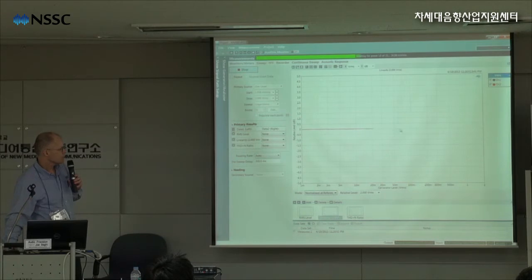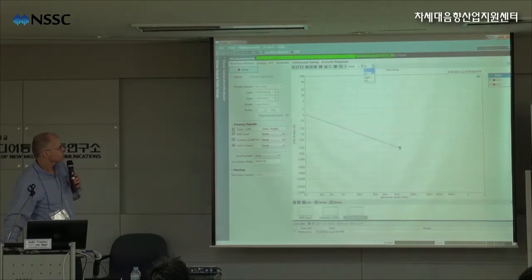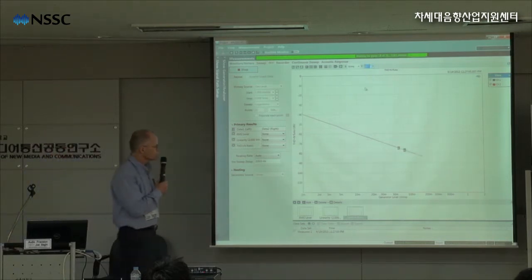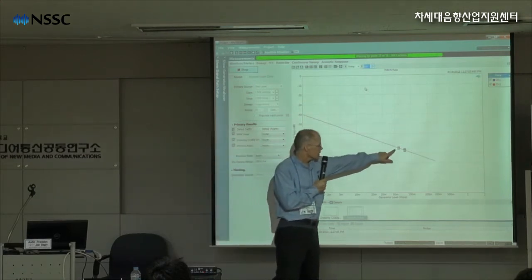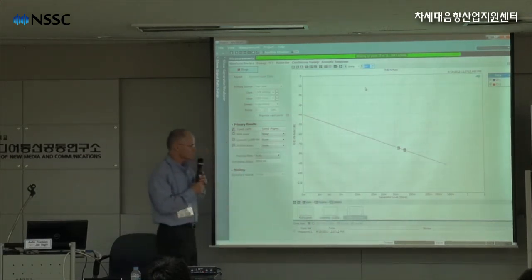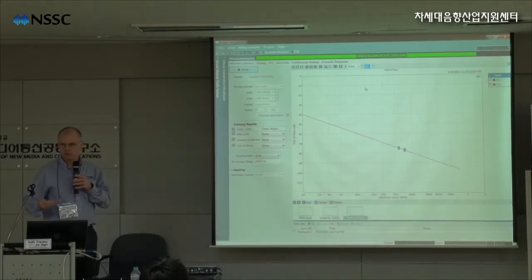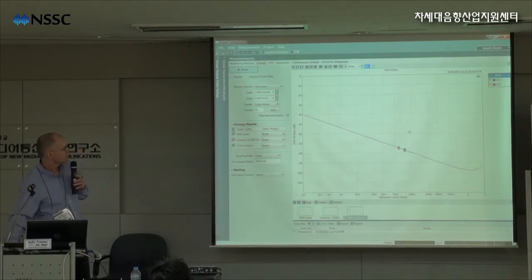Quite often when you get up to higher signal levels, the system will become nonlinear and you'll introduce a large amount of distortion. So here is the THD plus N ratio. Can change that to decibels. The T here indicates that there's a timeout on settling. So the analyzer uses settling algorithms to make sure that at every step change it's getting good data. Looks like we could go a little further here, but you can see the THD plus N starting to rise.